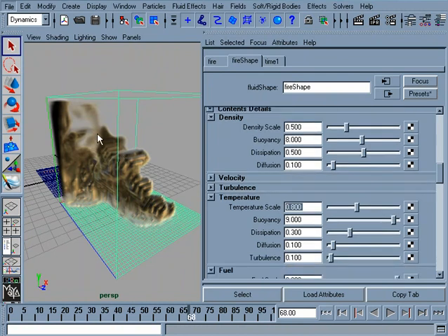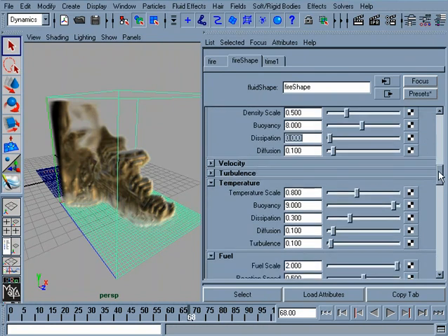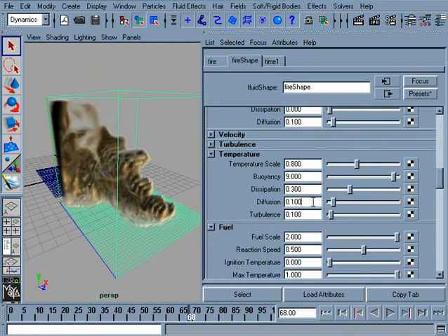You can see one of the things that this flame is doing is it's not quite as solid as the other one that we had. So again, this is because the higher fuel, or the higher temperature that this is burning off of, has kind of adjusted some of these settings that we had. So one thing that we could do to fix that is take this density dissipation and set that to 0, and everything else pretty much is set correctly.